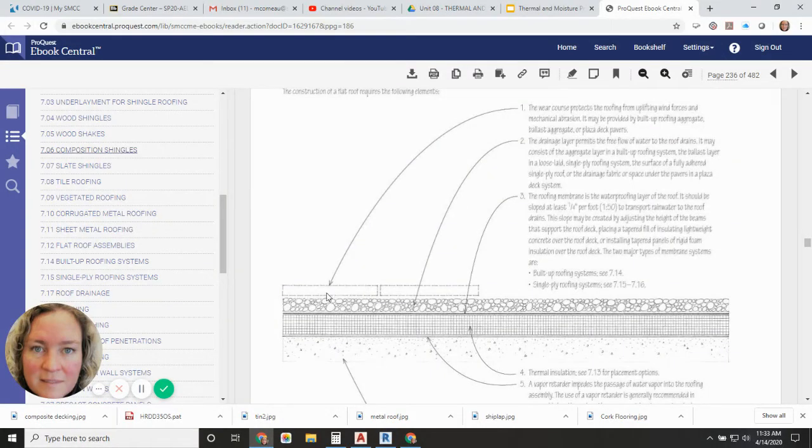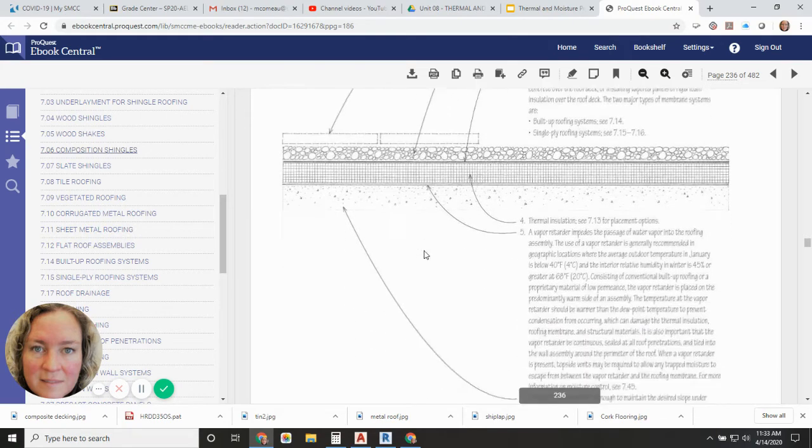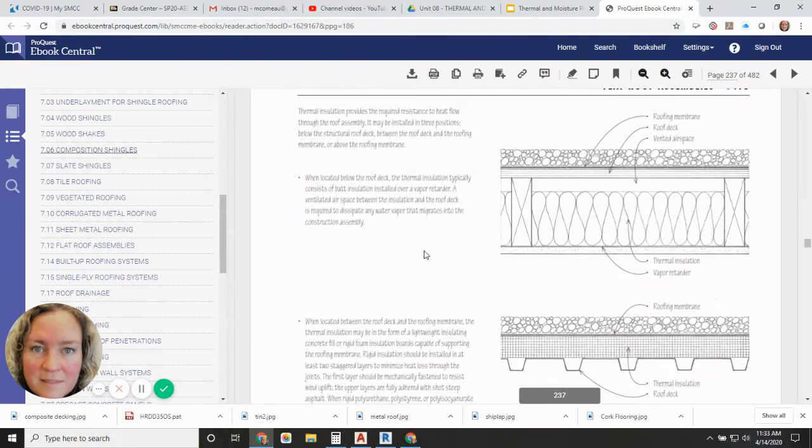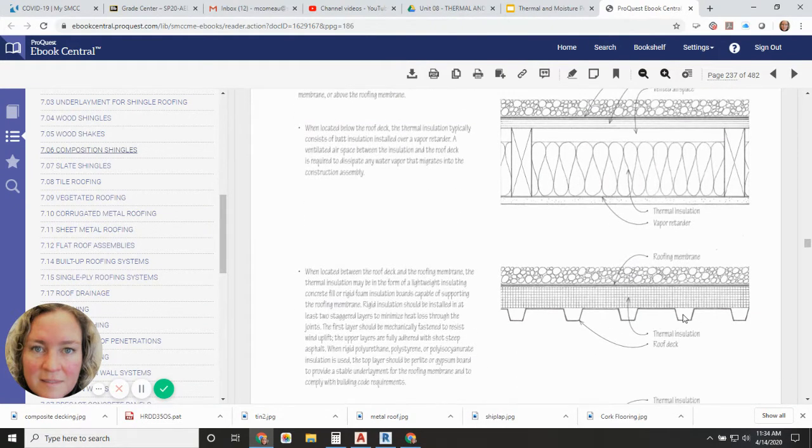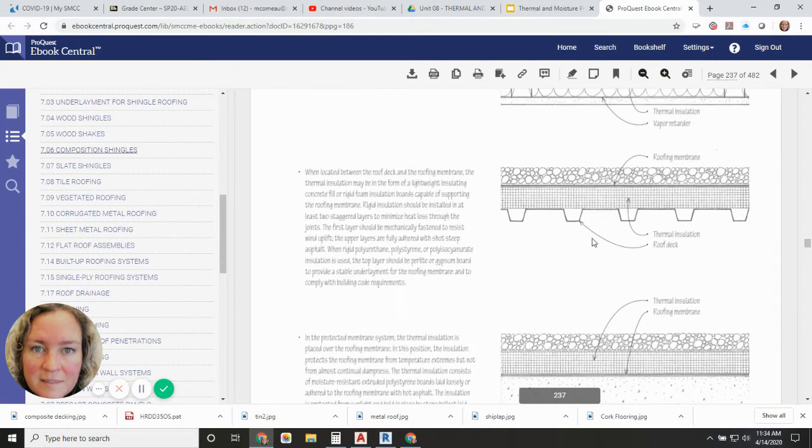And when you do this kind of roof system, especially flat roofs, they often get mechanical equipment put on top of it, and then paths need to be created for that mechanical equipment. And so they're showing here an example of how paths or routes that people are using to maintain that equipment will be designed into the roof system. So flat roof system on wood deck, flat roof system on metal deck, which is more common. And we have this, for instance, in our building at school. The Ross Tech building has this kind of roof system.